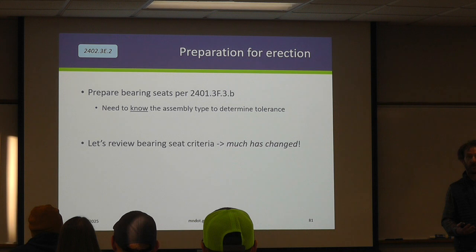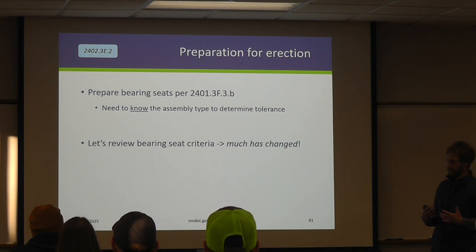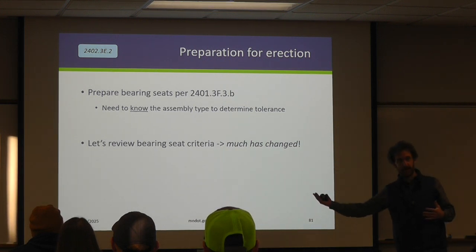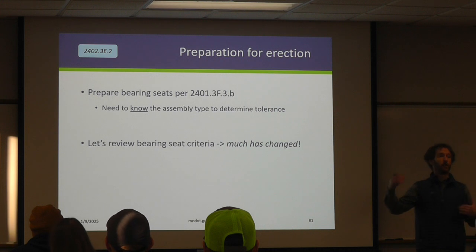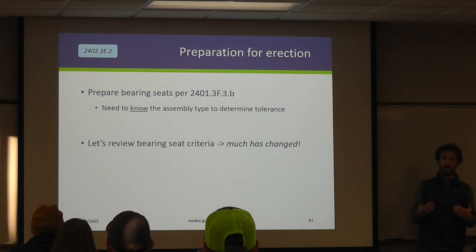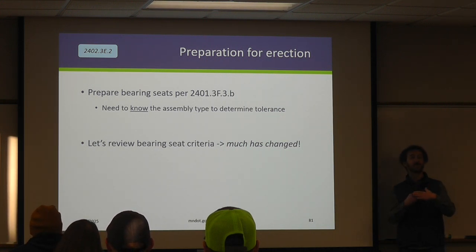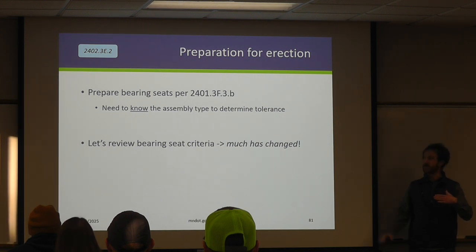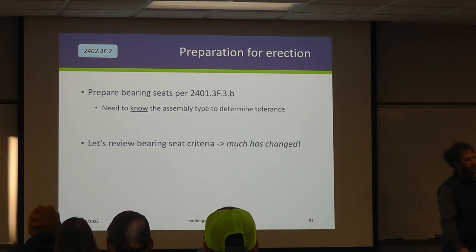3/16 and 1/16, or an oversized or a standard hole, right? Now, your ability to fit that up is going to depend a lot on how close to the tolerance your bearing seats are cast. If you only have a 1/16 of an inch slop, and let's say your bearing seat is an inch low, is that going to work? Not well. So we do spend some emphasis here on these bearing seat tolerances, because I've gotten burned on a project big time on this.